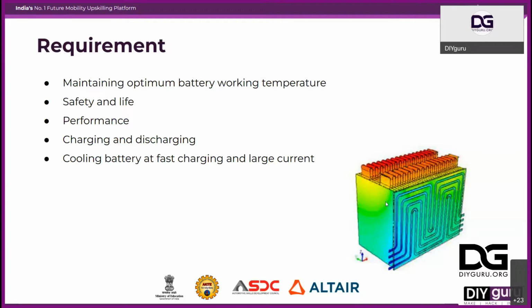That's why the four-wheelers that we have, if they were working at one C discharge rate, would require a very huge battery pack. That's why they have a very compressed size of battery pack and they have thermal management. For example, talk about the Tata Nexon EV. It works on a liquid cooling system, because of the 300-volt battery pack that it has.